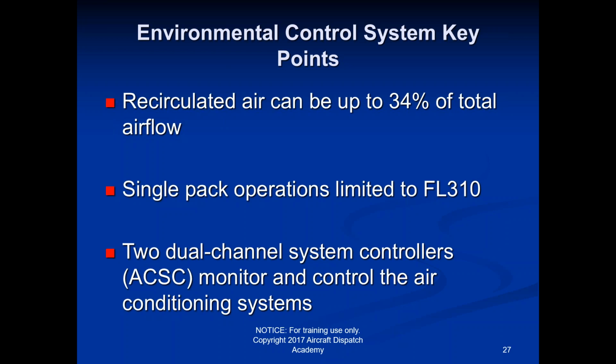It takes longer because, when we learned about air density and air pressure, the higher you fly, the less dense the air, the faster you can go. If you have to go down to 310, it's not like it's way dense air, but you have to fly at 310. It is going to burn more fuel than if you were flying at 37,000 feet. And it is going to take longer as well. So those things will affect performance.